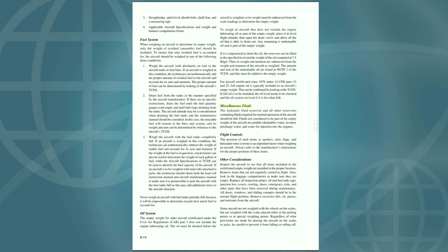Miscellaneous fluids. The hydraulic fluid reservoir, and all other reservoirs containing fluids required for normal operation of the aircraft should be full. Fluids not considered to be part of the empty weight of the aircraft are potable, drinkable water, lavatory pre-charge water, and water for injection into the engines. Flight controls. The position of such items as spoilers, slats, flaps, and helicopter rotor systems is an important factor when weighing an aircraft. Always refer to the manufacturer's instructions for the proper position of these items.